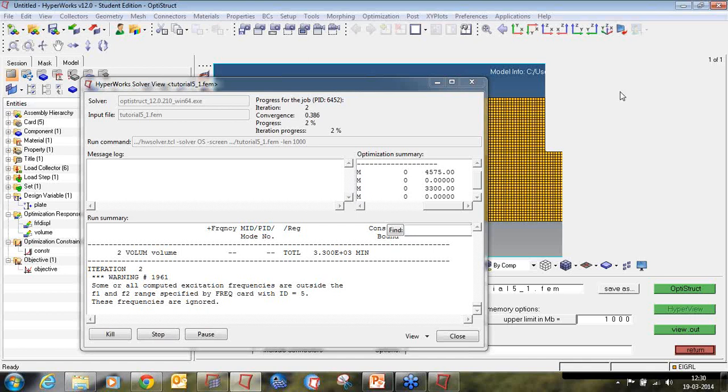In this tutorial, we will review an MBD transient analysis, change one of the rigid bodies to a flexible body, set up and run topology optimization on the MBD system using the equivalent static load ESL method, and post-process the optimization results in HyperView. We'll start by checking the file type. My file type is HM, so I will open the HM file.